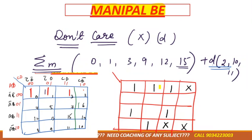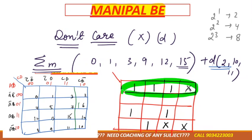Suppose now look here, if you don't include the don't care term, our groups would be formed like this, pairs of two, right? And I told you that instead of making pairs of two, we have to prefer more ones in the group, like powers of 2, so groups of 4 and 8 will be formed. So if I include don't care in my group, then I can make a big group, right? So there is my benefit in including it, so I'll include that one.